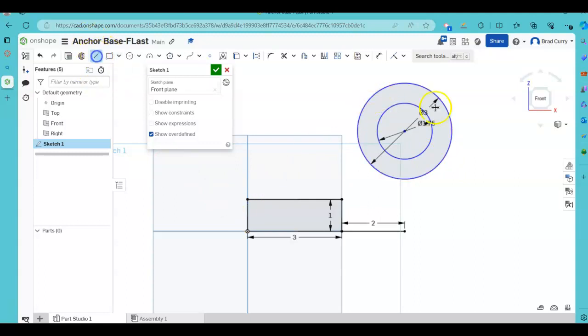So let me go to the line tool. Now in this case, I will select here to start, and we know that this should be tangent. So as you come up here, be careful. Make sure that you select and use the tangent symbol. To place that line, right click, escape out of the line. So let me come back, and now I'm going to do the same thing. I've got this line to go from here, and again, we want to make sure that this is tangent. So follow along until you get that tangent symbol to make that tangent. Left click, right click, escape to get it.